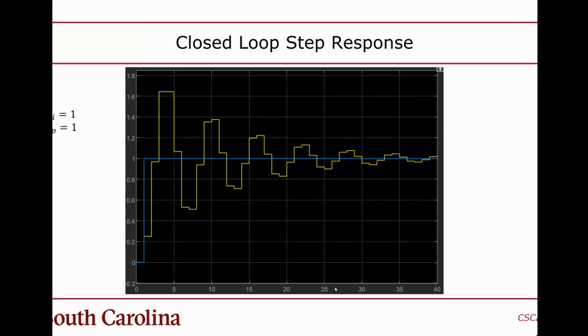controller I had for my little object moving system as I had with the S domain, but now it's in the Z domain. And in this case, I didn't do anything fancy like choosing Ki and Kp to guarantee stability. I got a little bit lazy here, and I just said, okay, I'm going to set Ki to 1 and Kp to 1, and that may or may not give me a stable system. I didn't validate that through checking the poles. But I simulated it, and it seems like it worked.